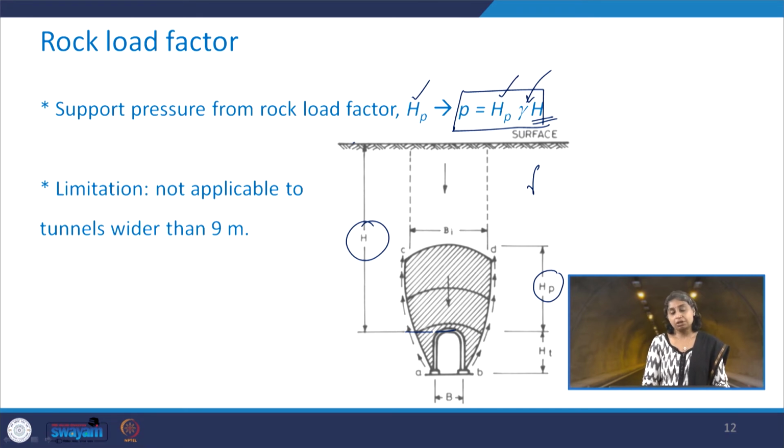The limitation of the use of this rock load factor is that this theory is not applicable to tunnels which are wider than 9 meters. So later on people have modified this theory to overcome some of such limitations of Terzaghi's rock load theory. That also we will see in this lecture.